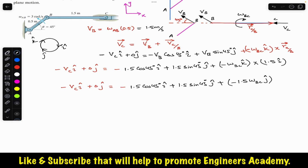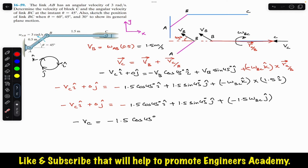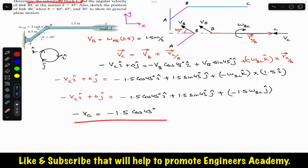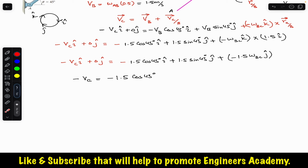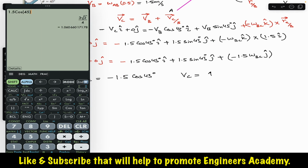So we can write that minus VC is equal to minus 1.5 cos of 45 degree. In the problem statement, we are only required to find the velocity of block C, right? So this gives us the solution. But if we were asked to find omega BC, we can further compare the j components. So from this we get VC. The minus sign will cancel out, and VC will be equal to 1.5 cos of 45. So VC is equal to 1.06 meter per second.